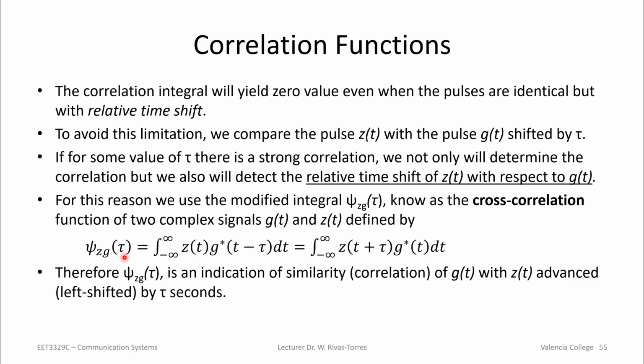For those of you who have done convolution before, the equation is very similar to convolution, except that in convolution you create a mirror image of the second function and then slide it across. In cross correlation, we do the same thing, except that we don't have to mirror the other function before we move it across.